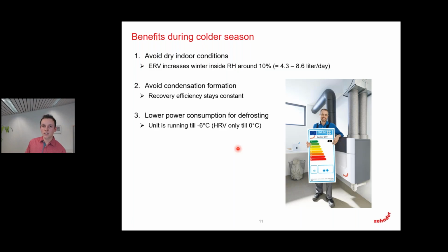If you still want ventilation below these temperatures, the preheater, as the name already says, preheats the air which is coming into the unit, so that there's no risk of freezing. Logically, the preheater, which starts at 0 degrees, has a higher electricity consumption throughout the whole year than the one which just starts at -6 degrees.